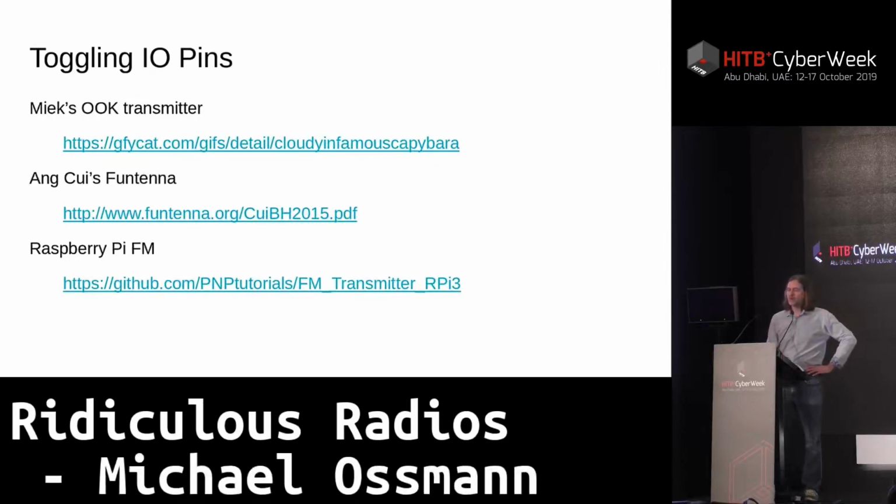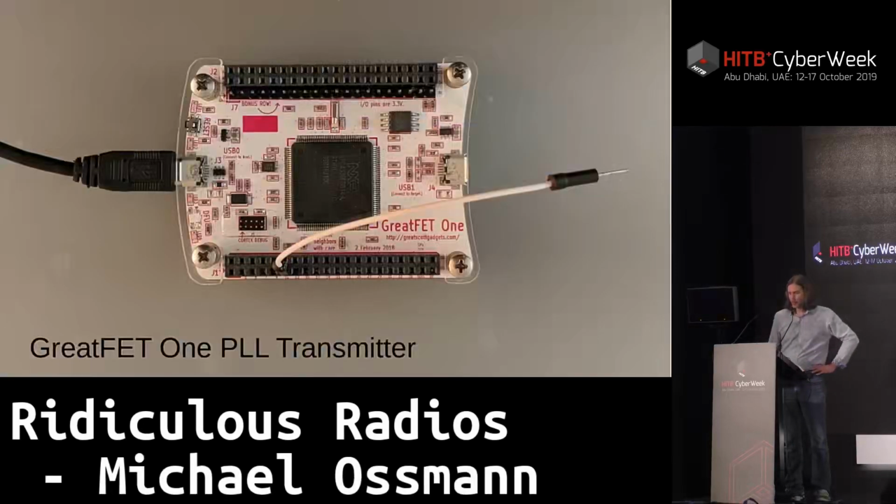And perhaps the most famous one is PiFM, the Raspberry Pi FM transmitter that was implemented in a similar way to what I'm about to show you, by using the clock generator that's built into the Raspberry Pi's CPU. Now, one thing that we did here was we made an even simpler circuit than the previous one. In this case, we have no components whatsoever except for an antenna.